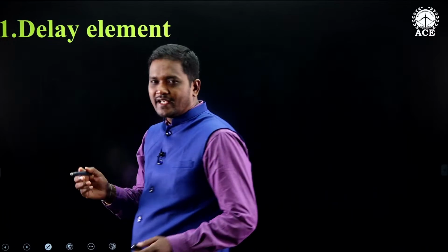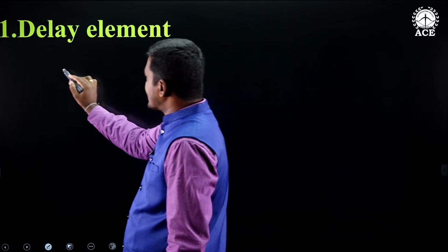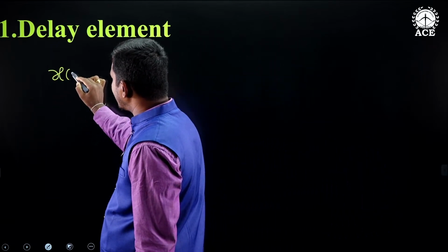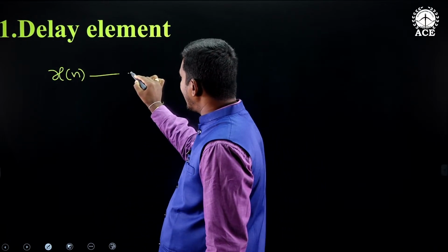Just now we have seen the difference equation. What terms are appearing? n minus 1, n minus 2, like that. What are those? They are delays. And in the transfer function we have seen z inverse, z power minus 2. What are those? Delays. So how to implement the delays? See here. Suppose x of n, a signal, is there. How to get x of n minus 1 is by using a delay element.